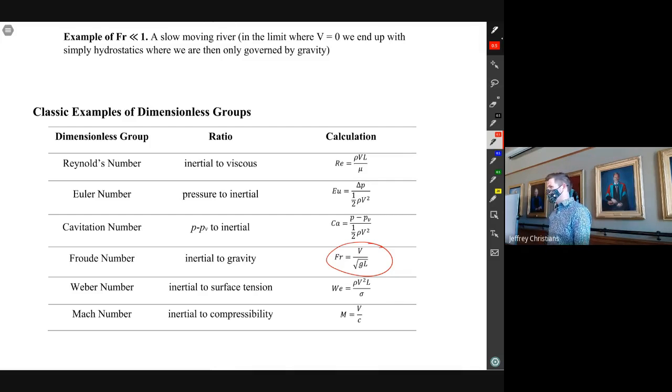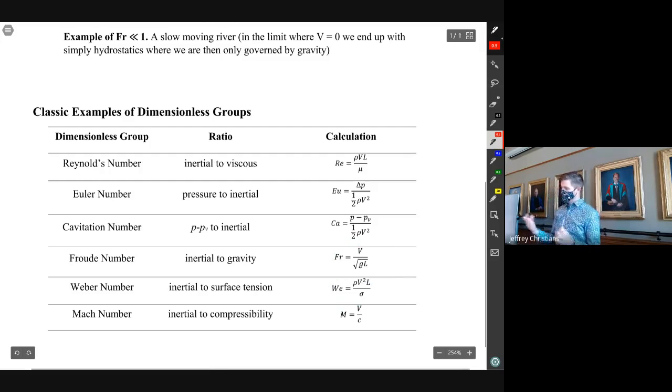Surface tension, I don't know if that's important. I've never really looked at this fluid or this size system. We'll spend 30 seconds, calculate the Weber number. Is surface tension going to be important? So that's the power of some of these groups, where without really any advanced calculation, you can get intuition as to what factors are going to matter and what factors aren't.